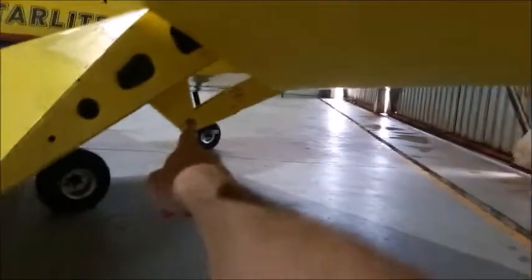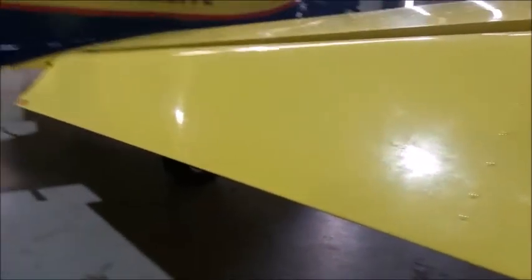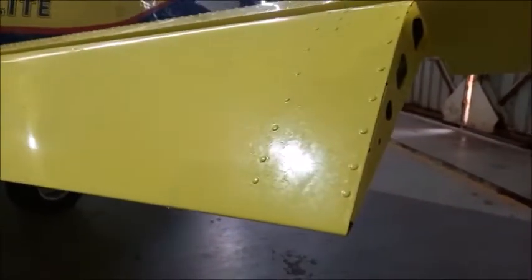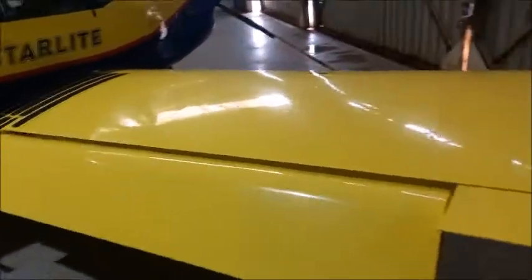We then have to look at the ailerons. These are the ailerons that make the aircraft roll to the left and to the right. We've got to make sure that all the nuts and bolts are in place. We don't want to lose control of the aircraft if these are missing. Also, when it comes to the flaps, we will be looking at those nuts and bolts as well. So the flaps are secure. The flaps essentially create drag on the aircraft. So when we bring the flaps down to different stages, it will create drag and allow the aircraft to go slower. And then again over here we will just make sure that the nuts and bolts are in place.